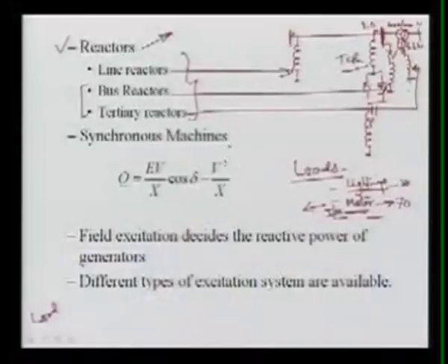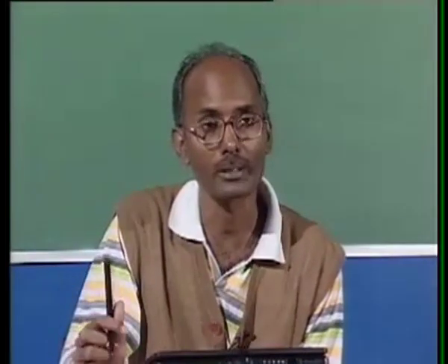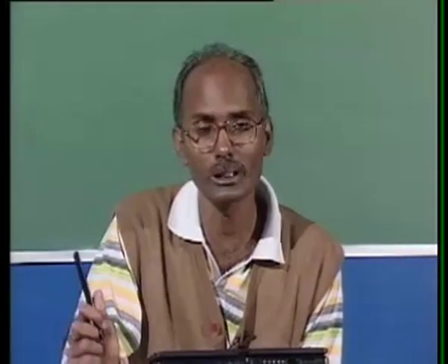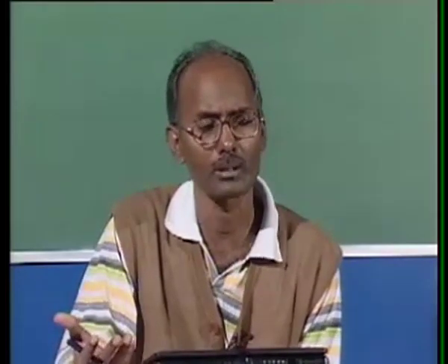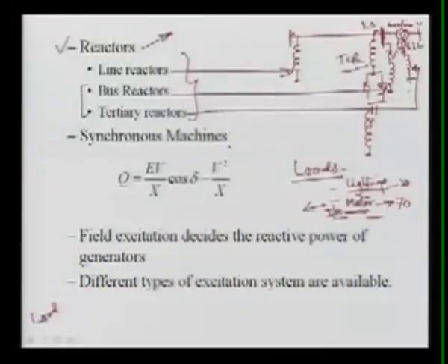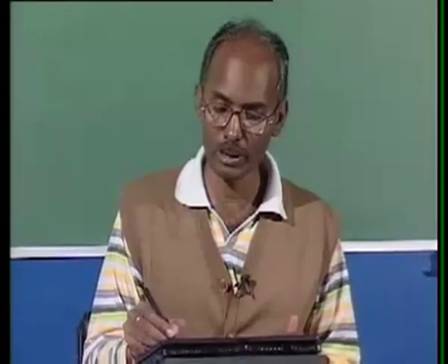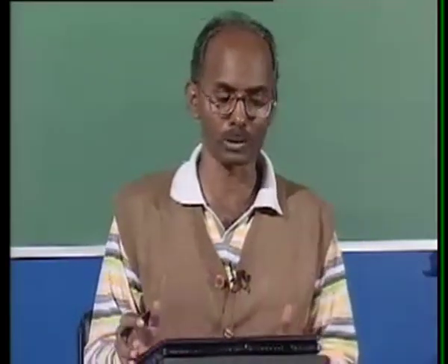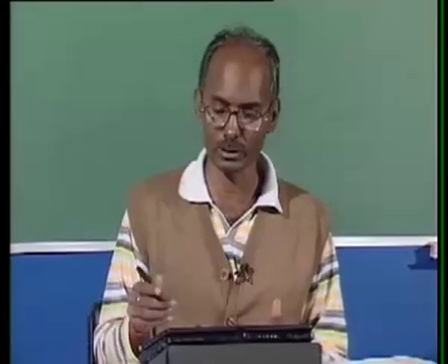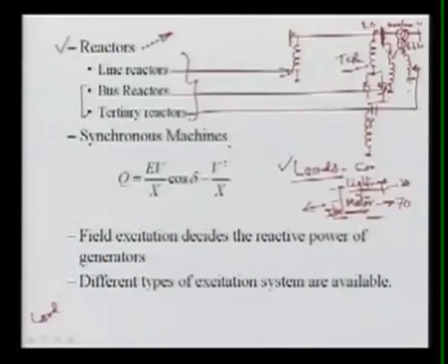Lighting load again depends upon which type of lighting you are using. If you are using a simple bulb, the power factor is unity and it is neither consuming nor generating reactive power. But if you are using fluorescent lamps or another type of lamps, what happens? In the CFL, they consume a huge amount of reactive power, and that comes into the picture. So if you add all the loads, not a single load, the loads mostly work as consumers of reactive power.